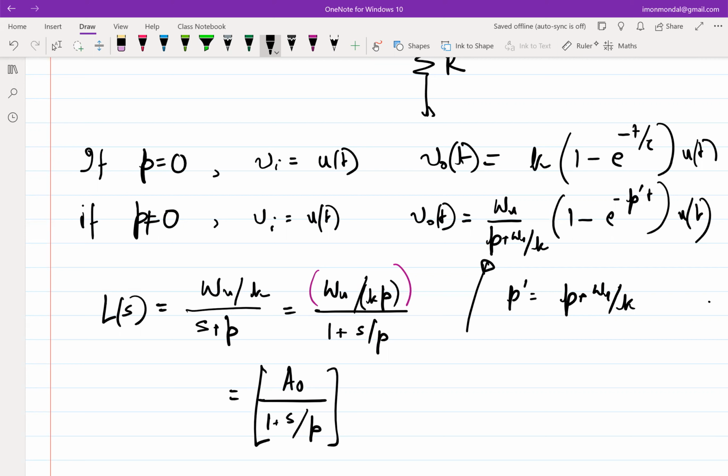Now, one of you said that it's supposed to be 11 because it's 1 plus. But note that I haven't drawn the phase part as yet. If there is a phase part to it, then this loop gain is not fully real. There can be a complex number associated with it also. So in that case, you cannot simply say 1 plus 10. It can be 1 plus some number whose magnitude is 10. So you'll have to be careful with that. By the way, any questions?